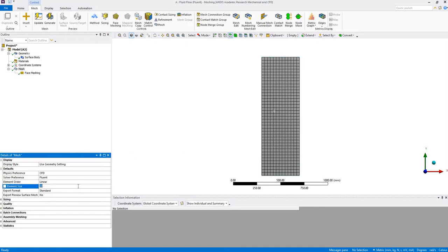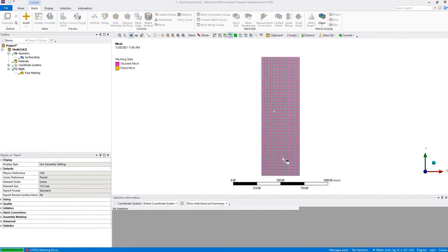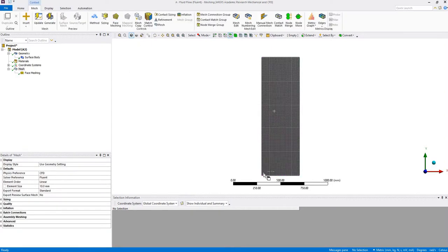And for a multiphase problem like this with particles, I would recommend using a uniform mesh all over the domain, even though you know that it's important for the fluid at the edge. Use a uniform mesh all over the domain. It helps solving for the particle phase. Okay, so this is one recommendation.